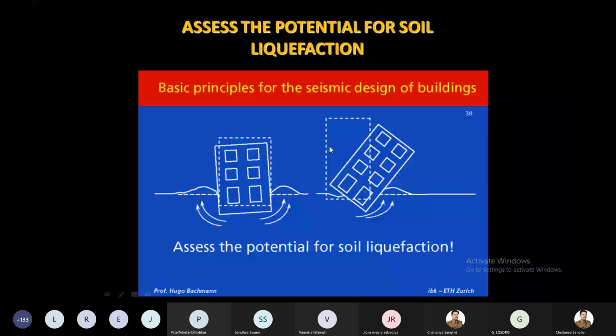So in case of a cohesionless soil, suppose your structure is resting on cohesionless soil, then what is going to happen? Then, during an earthquake, if the water table is high, water will come up, and the space between the particles is filled up with water, and then the friction will be eliminated and there will be no friction. So in cohesionless soil there is no cohesion, and now because of the rise of the water table, there is no friction.